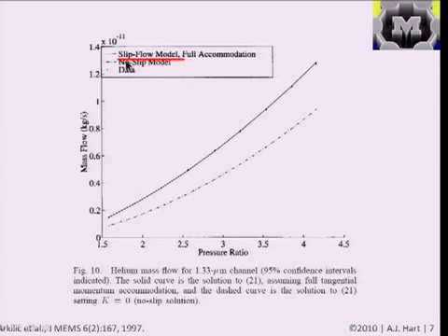And the two curves here show the result for the slip flow model and the result for the no-slip model, which they calculated from the theory that we discussed, and it's in the paper. And this shows their data. And their data agrees very, very well with the model for slip flow through these channels. So it shows that not only is the expression we discussed and the approach we discussed very accurate, but it's also a validation that it's important to consider these effects for these sorts of geometries.